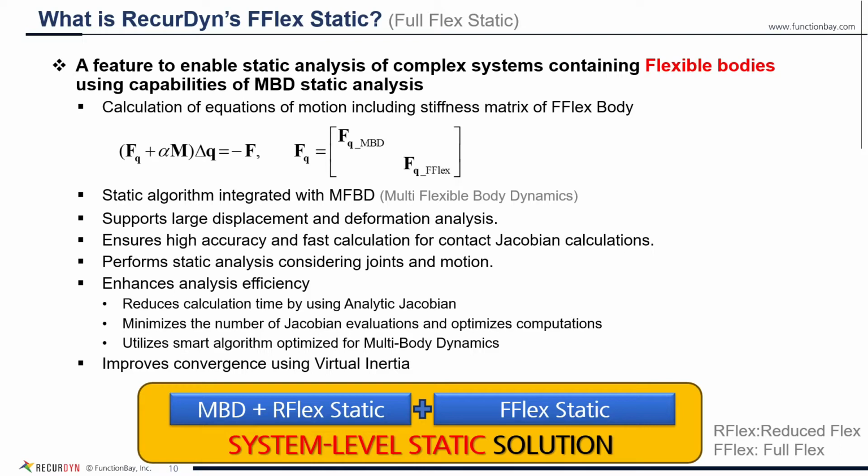To make this functionality possible, FunctionBay developed a static analysis solver specifically for MFBD equations of motion. We also enhanced the accuracy of Jacobian calculations for contact equations and implemented numerous technologies to improve computational efficiency. This groundbreaking feature took several years to complete. Now, static analysis is possible for highly complex mechanical systems that include rigid bodies, R-flex bodies, and F-flex bodies.